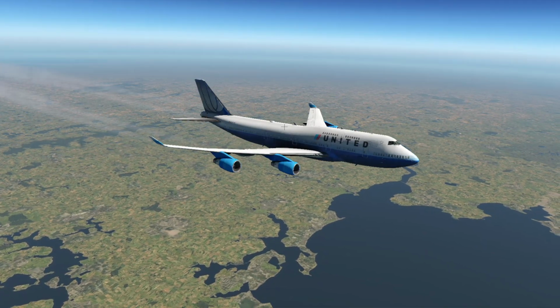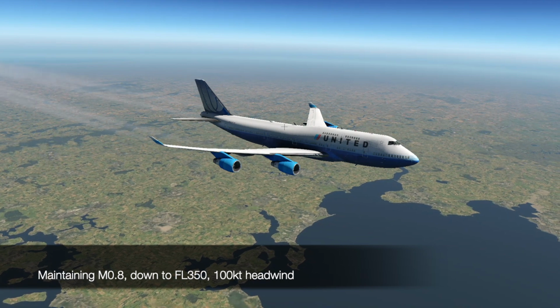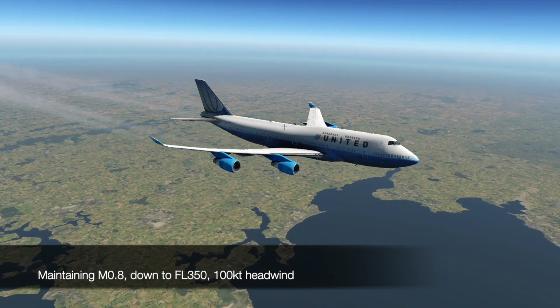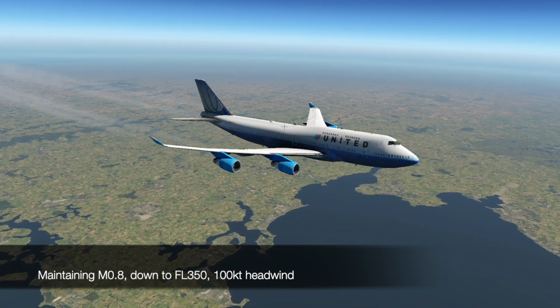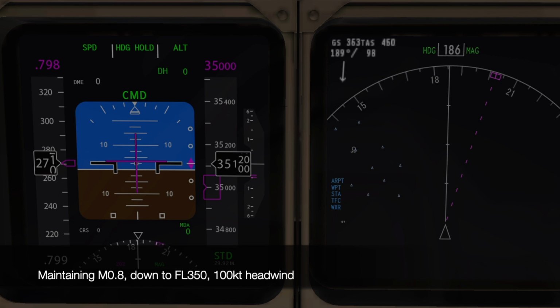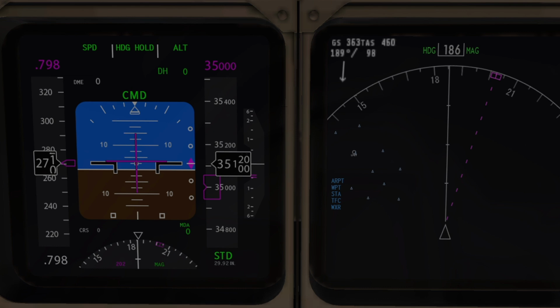Now, let us imagine that we have descended by 5,000 feet to 35,000 feet, but we are maintaining the same Mach number of 0.8 or so. As we jump into the flight deck, first we note that the true airspeed is broadly the same, 460 knots, actually accidentally exactly the same, with the tiny shortfall in Mach number cancelled out exactly by the minimal change in temperature and thus in speed of sound between flight levels 400 and 350. As expected, the calibrated airspeed has increased by a significant margin of nearly 30 knots. The ambient density here is about 25% greater than it was 5,000 feet ago.